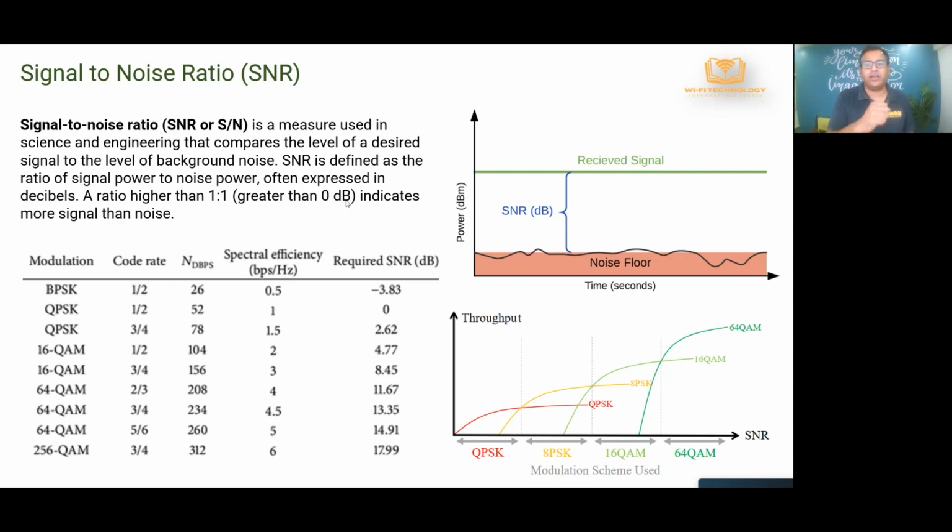And now you're raising the signal with respect to the noise floor. Now all the receivers can hear you again, even though there is a lot of noise, because you've raised the signal power, right? So to have a high SNR or signal to noise ratio, either you increase the signal or you reduce the noise. Either way, the ratio of signal to noise should always be higher, right? So that is the idea of having good signal to noise ratio.